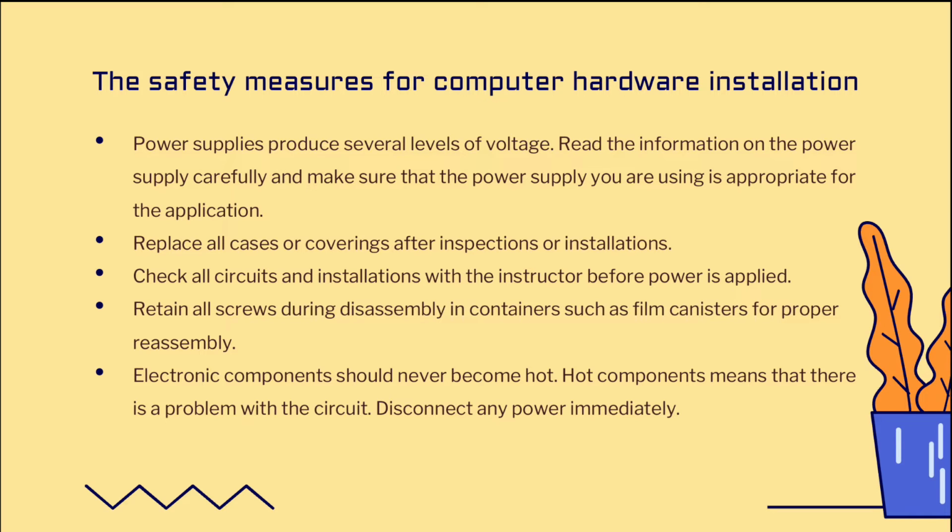Retain all screws during disassembly in containers such as film canisters for proper reassembly. Electronic components should never become hot. Hot components mean that there is a problem with the circuit. Disconnect any power immediately.